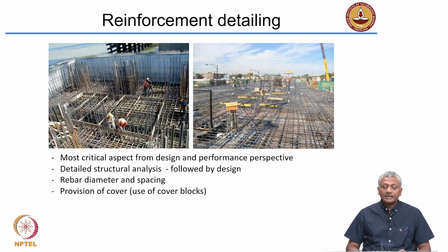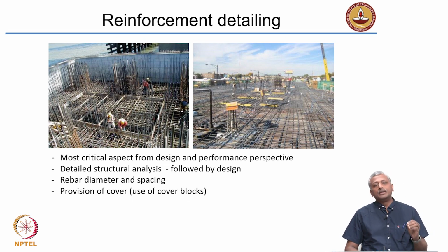In most cases, from the design and performance perspective, in a reinforced concrete structure, the steel reinforcement detailing is perhaps one of the most important aspects which will control the performance. Now, as I said, you need to do a detailed structural analysis and determine where the tensile zones are, where are you getting tensile loading, and the design basically incorporates concrete and steel in such a way that the steel is distributed evenly in the zones that need to carry tension.